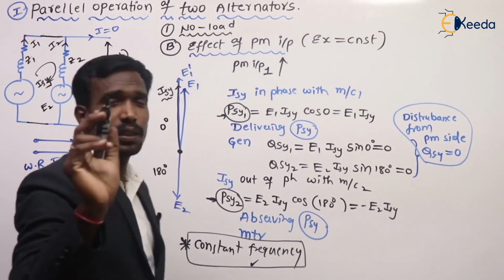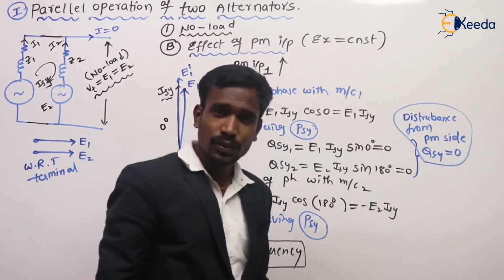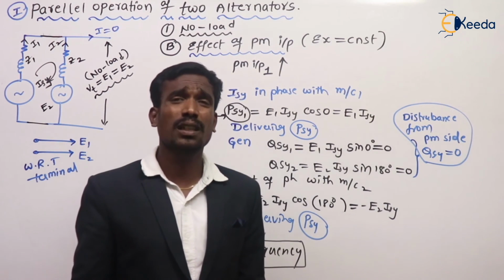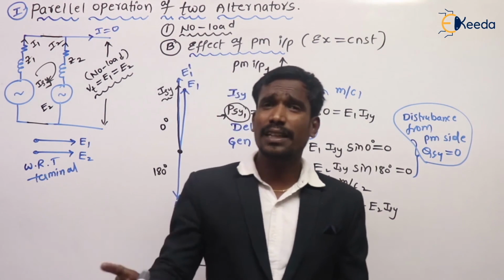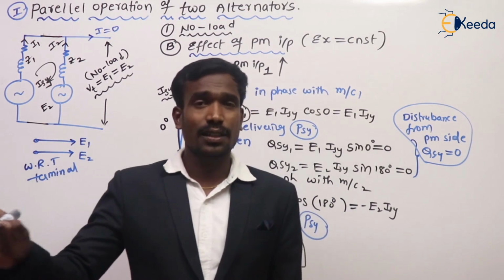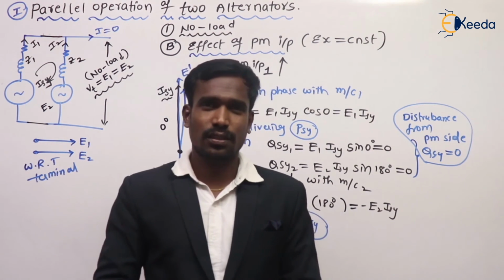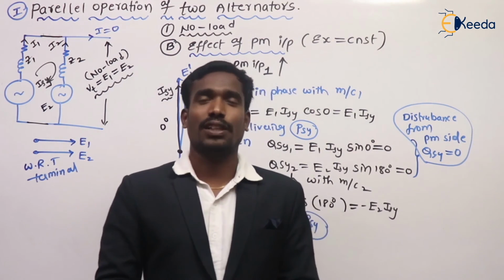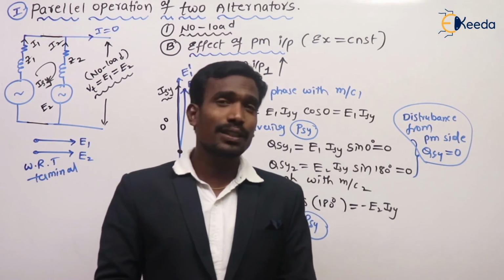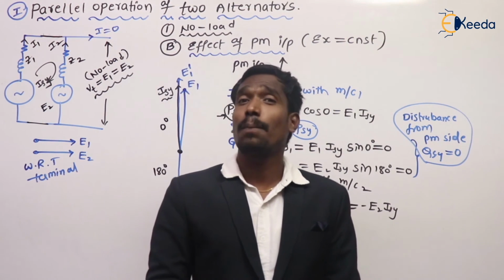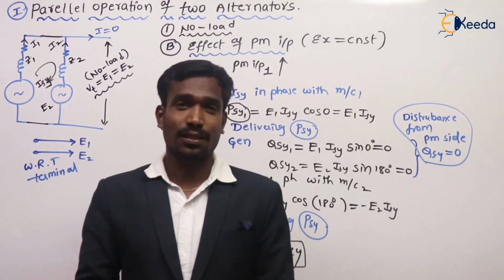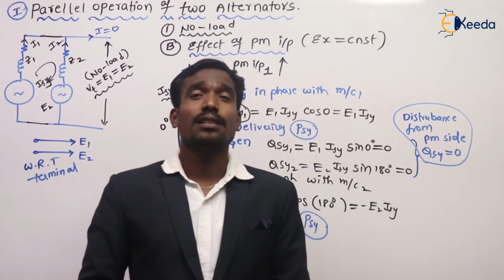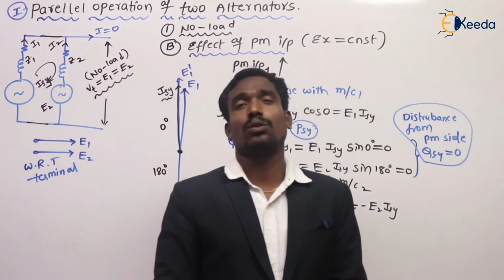You have to remember this point. Okay, so what is the conclusion? When the excitation changes, reactive power will change. When the prime mover input changes, active power will change. In both cases, synchronizing powers come into action. But if the disturbance is from the excitation side, synchronizing reactive power comes into action.